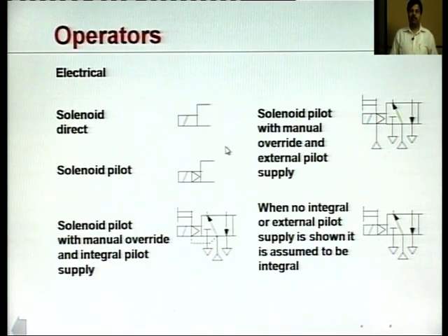In addition, we can also use some electric system or solenoidal system in addition to the mechanical system, pneumatic system, or whatever we have discussed earlier. A solenoidal system has an electric system or an electromagnet connected to the main shaft of the valve. So that when we supply electricity to this solenoid, it becomes operational and it pulls the valve in one direction,